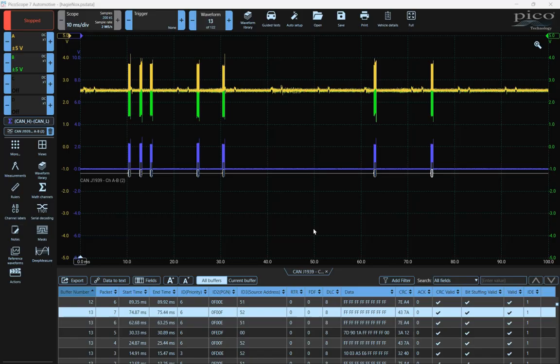The same thing for the DEF quality. It isn't something that we're going to expect to see that quality change, except whenever I fill the DEF tank, right, or over a long period of time. So that's a message that is not going to be broadcast very often. And so I would have to have my failure in place, in this case, a wire to wire short or a short to ground of CAN high. I would have to have that in place long enough for probably 5 of those messages from the DEF header to be missing. So that could be several minutes of time.